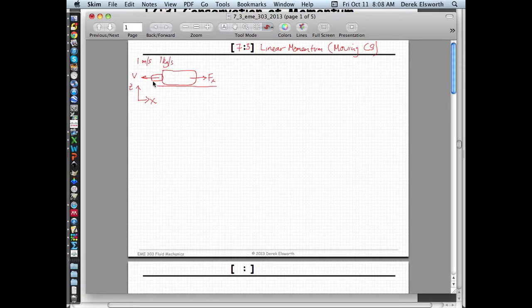So there's something coming out of here, the only place it's coming out is the tail end of this decapitated cylinder. This would be the nominal scalar magnitude of velocity, and this the nominal scalar value of mass flow rate. No directions. So it's coming out backwards, pointing towards the minus x direction, at 1 meter a second, and it comprises 1 kilogram a second.